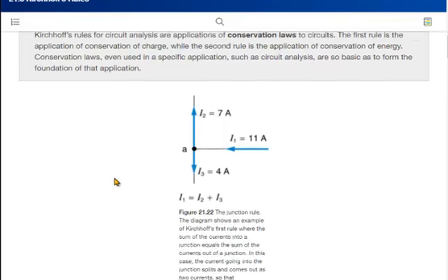The other one is for the parallel one, so let me scroll down. These here are all kinds of examples. So here's the parallel one. Here, of course, the surprising result is this one right here: the reciprocals, and that equals the equivalent resistance also as a reciprocal. Where does that one come from? Well, it also comes from Ohm's law. This is the junction rule, Kirchhoff's junction rule. And so the electric currents add up, getting the total current. Then the voltage is the same for each part in a parallel circuit. And you plug in Ohm's law. And then because the voltage is the same, that actually divides out or can be factored out. And what remains then is the reciprocals.